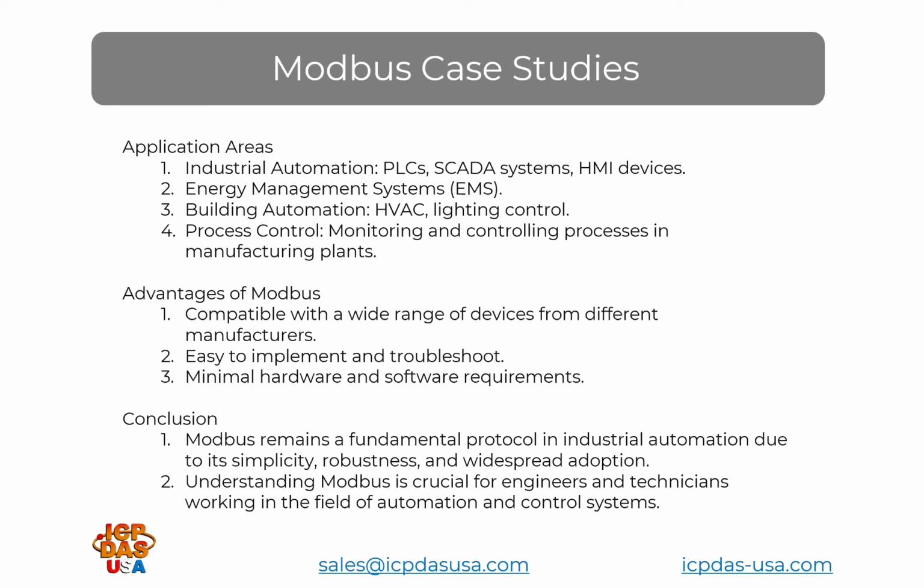Well, the one I'm working with right now only allows you to pull 40 registers at a pull, okay? And then they have to start on the 40 boundary. You can't overlap the boundaries, even though there's registers there. Otherwise, you'll get comm errors. Okay, yeah, that's based on the manufacturer.